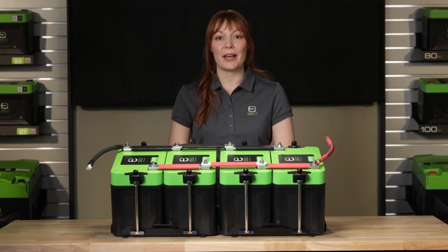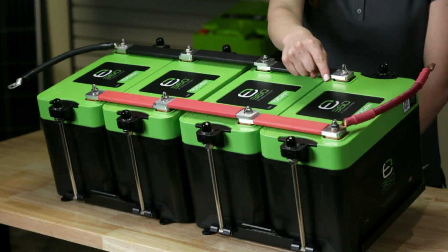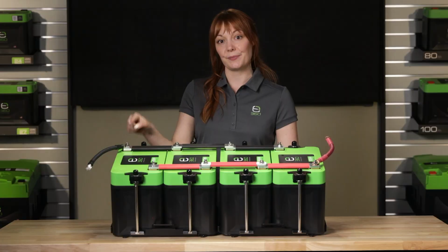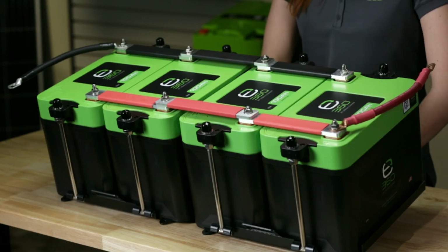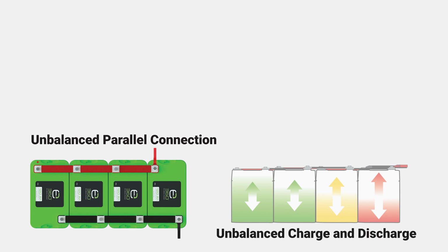For parallel wired battery banks, we recommend that it is best to pick up the positive terminal at one end of the single parallel string and the negative terminal from the opposite end of the string. This is done in an attempt to balance the amount of current and voltage running through the string during charge or discharge. Feeding the string from one end can cause a voltage or current imbalance, which is why we don't recommend using that configuration. Each pair of interconnecting cables will introduce additional resistance until the last battery ends up with the highest resistance path to the attached load.